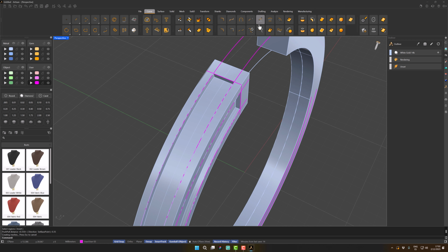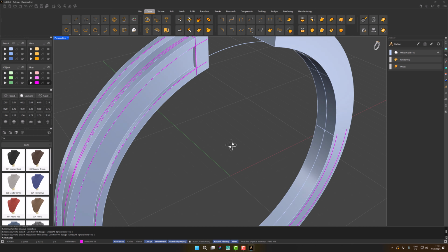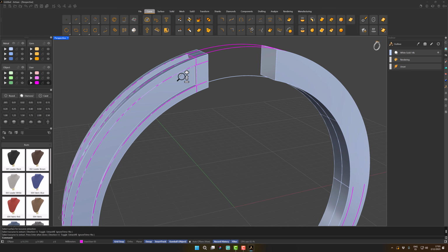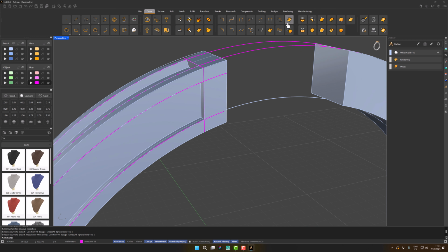Go to the Curve tab and use the Extract IsoCurve command. Select the solid and ensure the direction is set to you. With the help of OSNAP, click on the channel's midpoint. For the lateral part, use the Offset curve on Surface command. Select a channel edge and type 0.75, which is half the channel width.